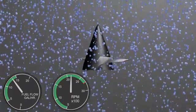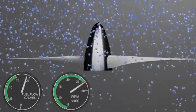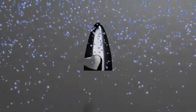Seems obvious, I know. But now let's compare this to a constant speed propeller. At top of climb, we'll reduce the propeller lever instead of the throttle. The propeller lever doesn't affect the engine directly, it turns the blades coarser to force that decreased RPM. It's only the connected crankshaft that's causing the engine to slow down.